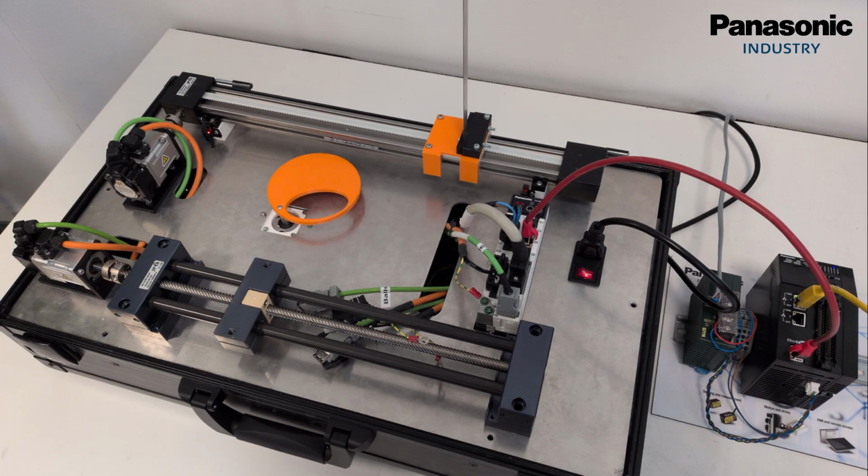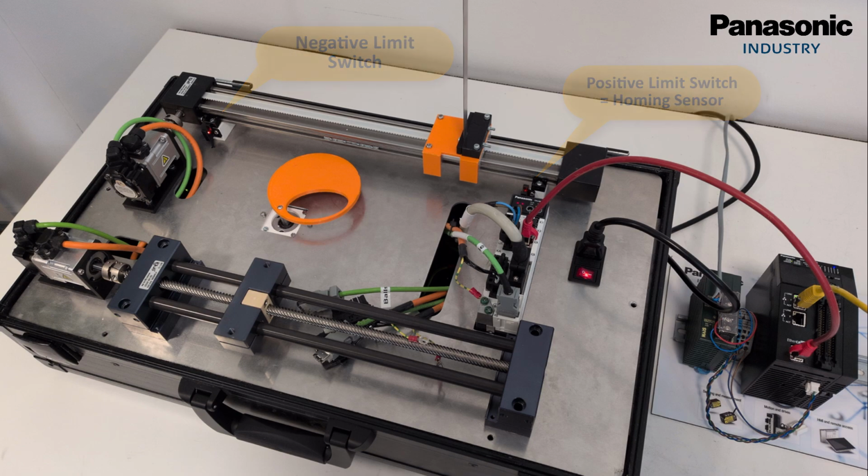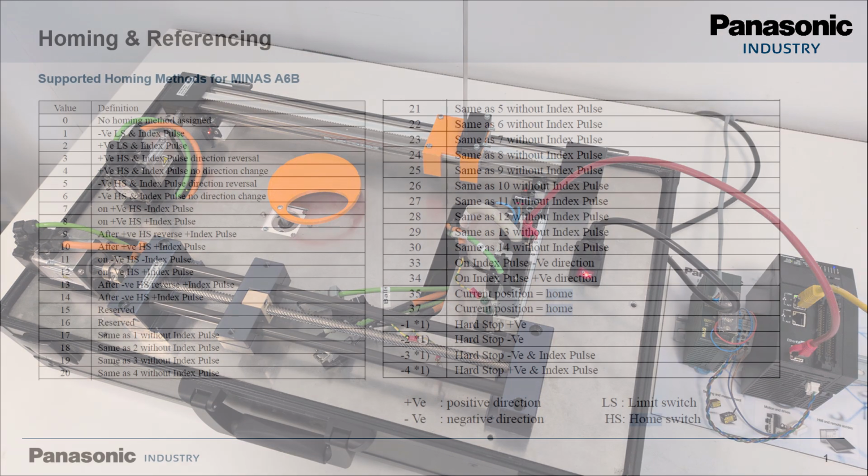To demonstrate this, let's take a look at our test application. We're using a tooth belt system directly connected to a servo motor through a servo coupling. On both the left and right sides of the belt, we've installed limit switches. In this setup, the right limit switch also acts as our homing sensor. First, let's demonstrate homing using an incremental encoder.